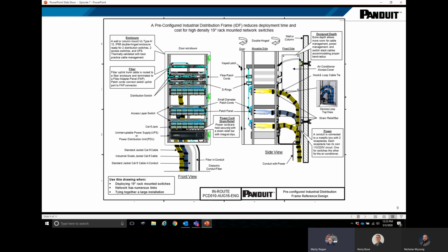The IDF can be a transition point for single mode to multi-mode fiber media used for the connection to the industrial switches for the controls network cells that are out of reach for the copper cable. The operations team would have easy access for maintenance, diagnostics, moves, or additions.